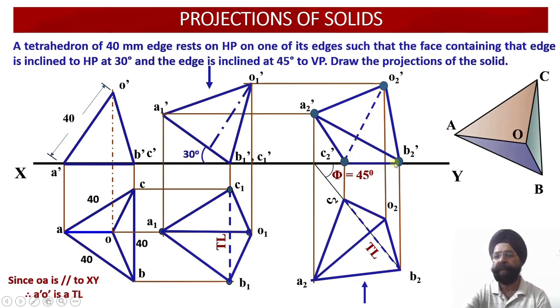Whereas the edge B2 dash, C2 dash, since it defines the boundary of the tetrahedron, cannot be dotted. Similarly over here, edge A2 dash, C2 dash is again defining the boundary of the tetrahedron. That is why this edge is again drawn by the object line or the darker line. Whereas there is no question about darkening of these 3 edges over here, because they are not passing through C2 dash. So all of these 3 edges will be drawn darker.